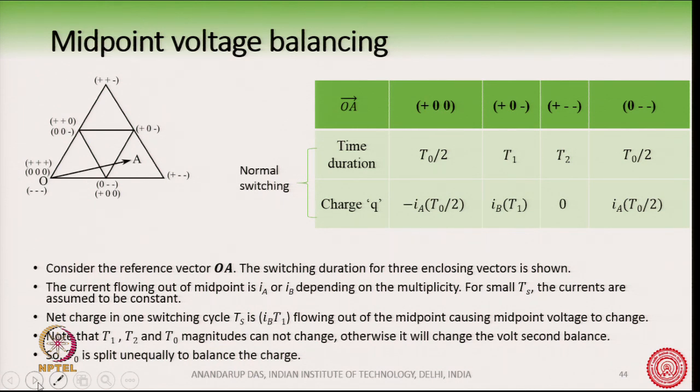First of all, the NPC has a single DC link for the 3 phases. That is one reason which the MMC does not have. The MMC cells have capacitors which are like a single phase supplying.